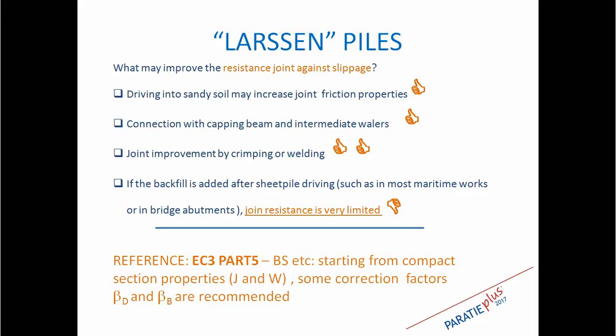But of course, if you drive a sheet pile first and then add a backfill, as frequently occurs in maritime operations, when you drive the sheet pile there is no soil, but maybe water only, and so in that case the joint resistance cannot be relied on.